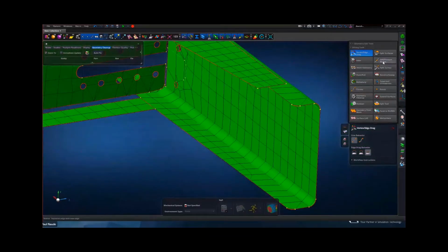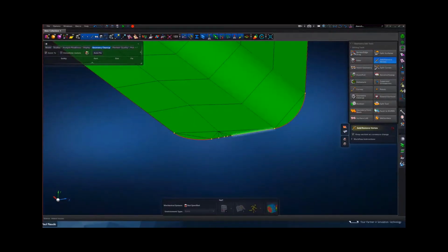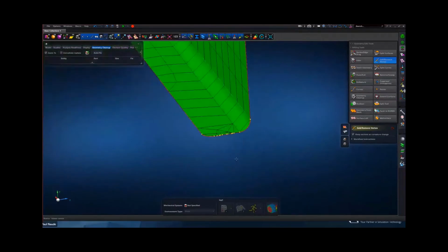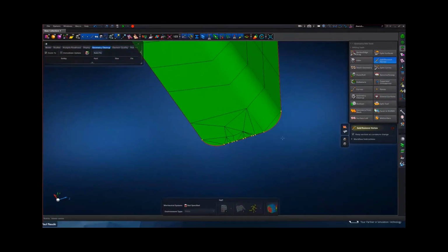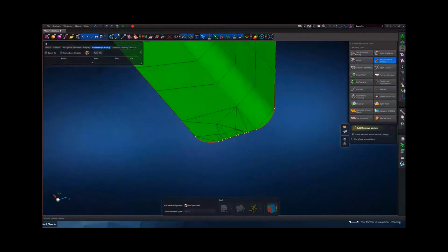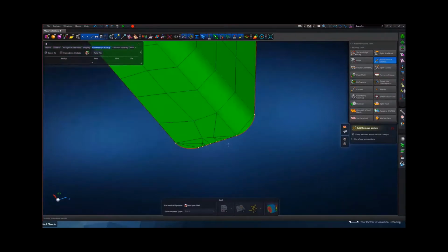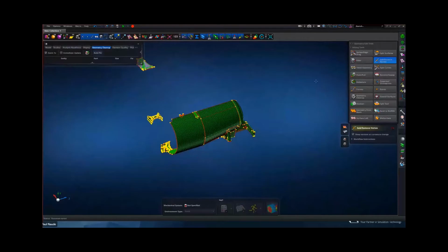Okay, so that's one of the tools, but often we sit with a CAD that we receive from somebody else, and depending on how they created the geometry, you might sit with little features that can't be ignored by the mesh, regardless of the mesh quality or mesh settings that you use. Those vertices always enforce a node at that location. And if this is the way that you receive them, it might be a lot of work to individually remove all these holes. Nothing stops you from literally activating the tool and dragging it over the whole model, regardless of what it is. And it will only remove the unnecessary ones.